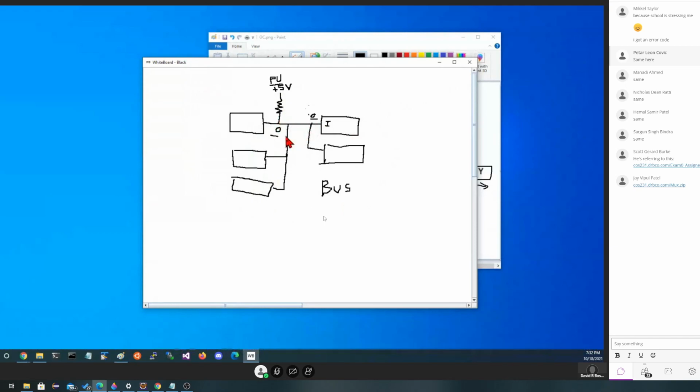So all we have to do is discipline them into saying only one of you at a time can write. We could control that by having them hooked to some sort of a sequencer. And a sequencer could be built just as a counter out of flip-flops or some sort of timing mechanism that said it's your turn, it's your turn, it's your turn.